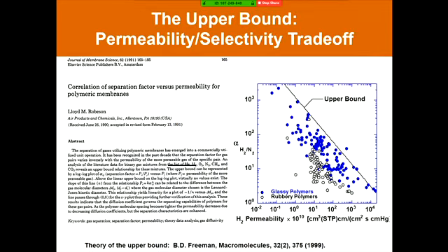What we also find is that as we vary the permeability of polymers, we cannot usually independently control selectivity. And so this is showing the hydrogen permeability properties of a variety of polymers plotted against their hydrogen over nitrogen selectivity. This was that ammonia purge gas application.